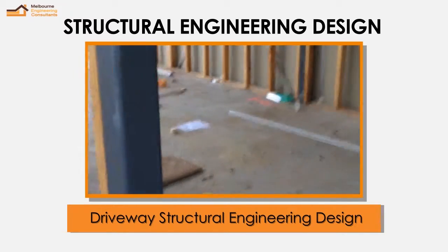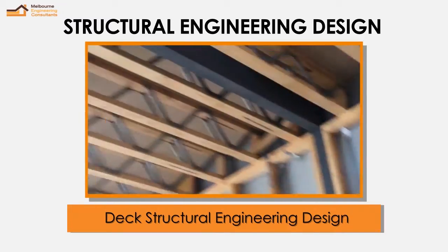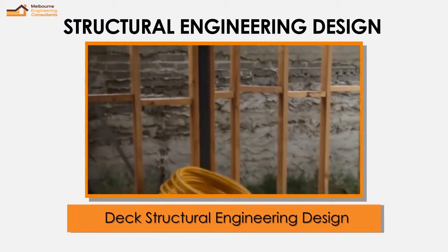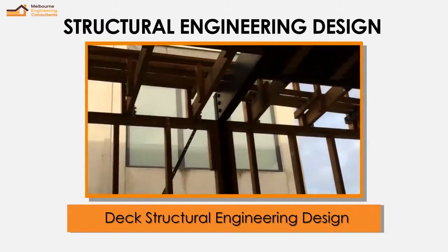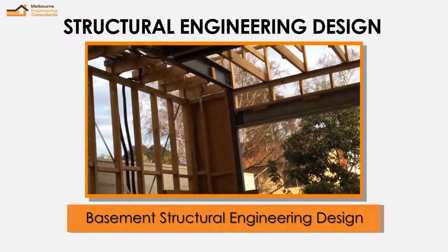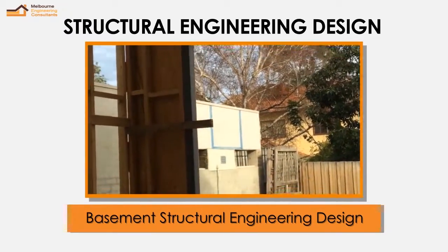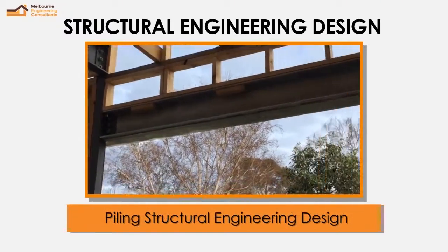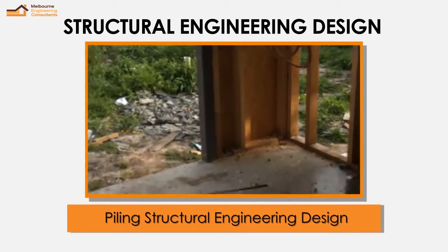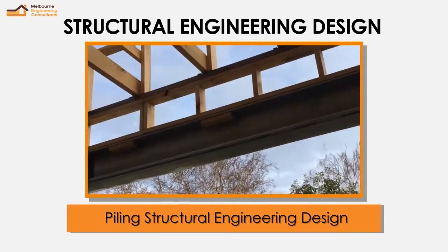Again, the steel beam frame connection, the steel post and steel beam, and again on the other side the steel post again with an M16 bolt connection, and the timber beam is connecting the steel beam and transferring the load on the side. These steel beams are also acting as a portal frame for the structure, which is required in terms of the stability against wind. And again here we have the wide open window, a sliding stacker door. The steel beam has been designed for it, and outside we have the brick veneer, which is going to sit on this steel beam and come up as a parapet, and it's a lightweight roof again.